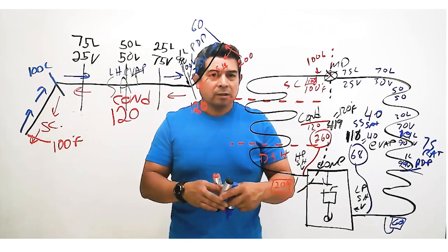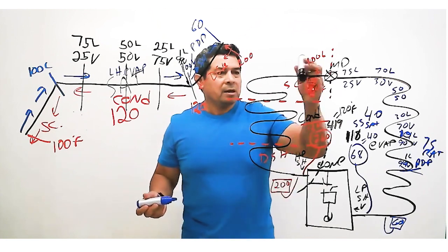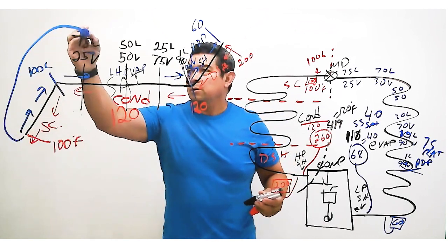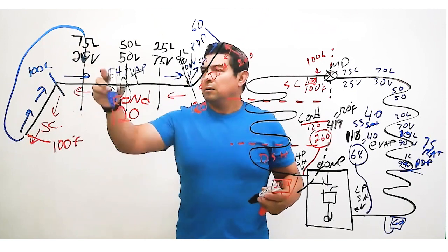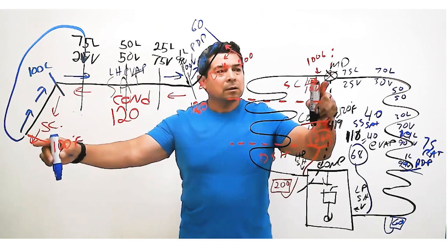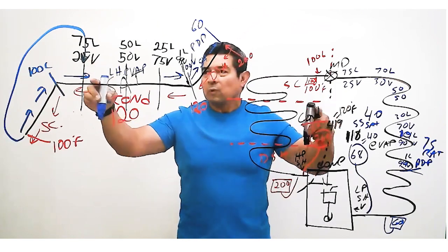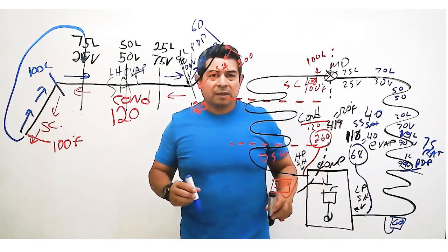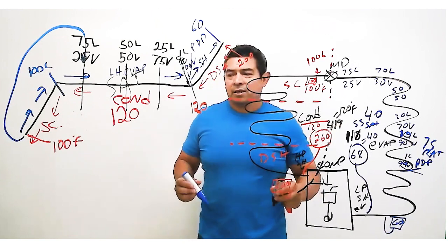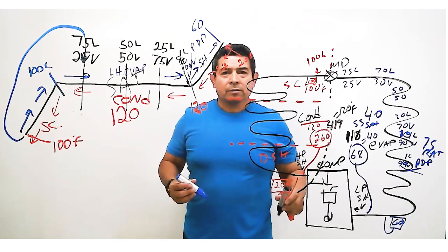The refrigerant now goes into the metering device. This is a little tricky because here we're at 100 degrees, and from here it jumps all the way up to right here: 75% liquid, 25% vapor. Because 25% of it becomes gas, becomes vapor, we have what they call flash gas. That flash gas is what makes the temperature drop. We drop that temperature, and now we're at 40 degrees.